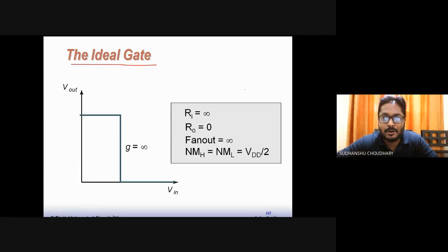and especially in the NOR gates where the pull-up network has, as I said, PMOS connected in series. So if the number of inputs is more in the NOR gate, the number of PMOSes connected in series in the pull-up network will be more. So the TP-LH delay will be more. The overall circuit can become slower and also more power hungry. So that is why a limit has been set on fan in. It should not be more than 4 or 5.